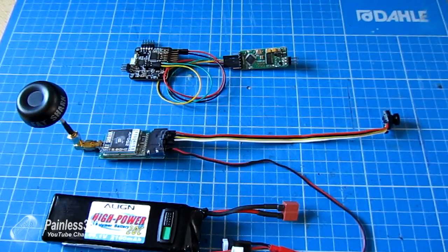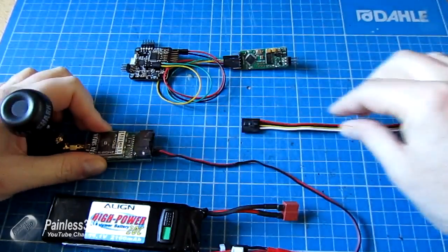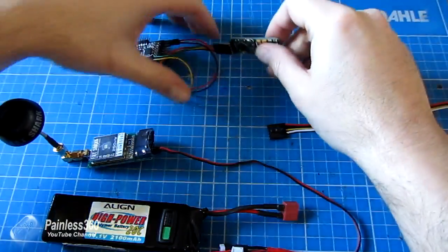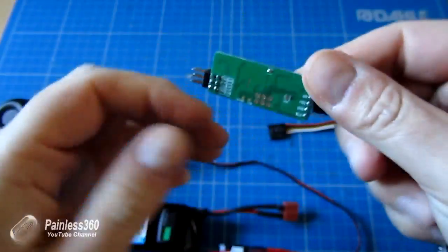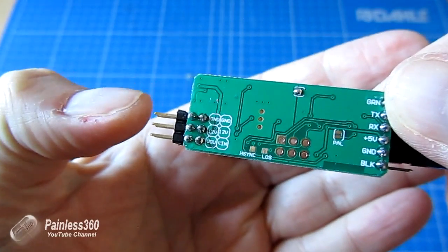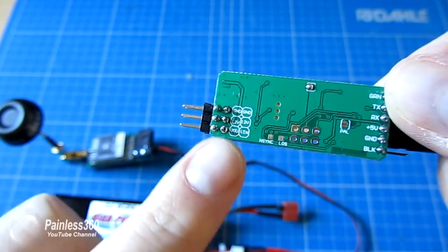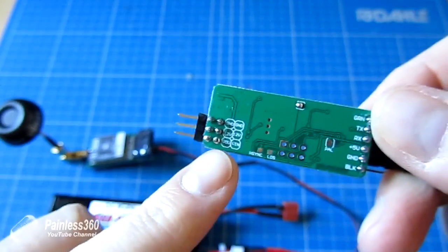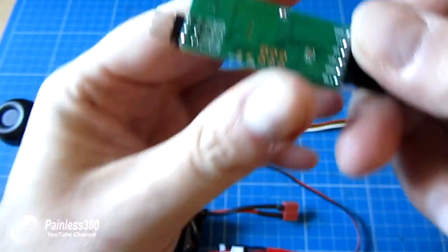So the first thing we're going to have to do is unplug the camera from the video transmitter, because the MinimOSD is going to go in between those two. Now on the back of the MinimOSD, you'll notice that it very clearly says which is the ground, which is the voltage, and which is the video in and out. That is video in and that is video out. Be very careful when it's a right angle pin, it's easy to get confused. So video out is on the bottom.